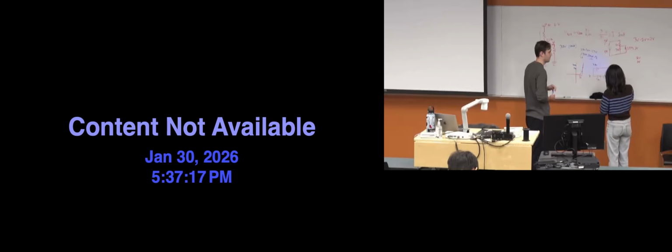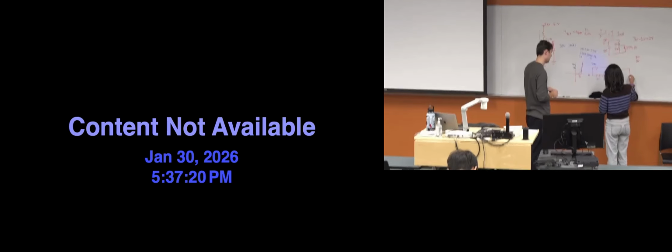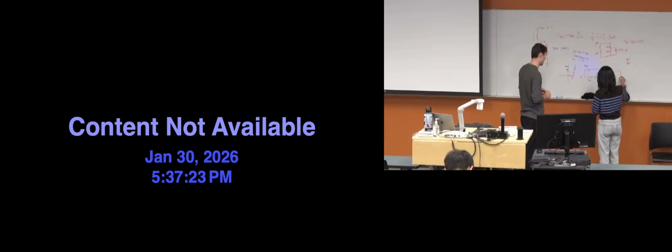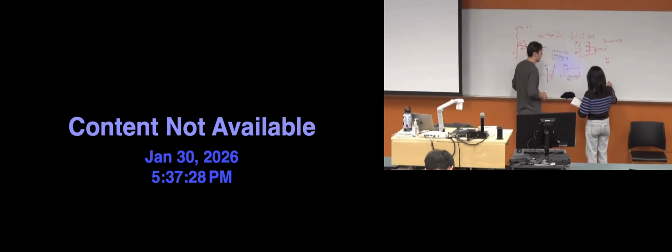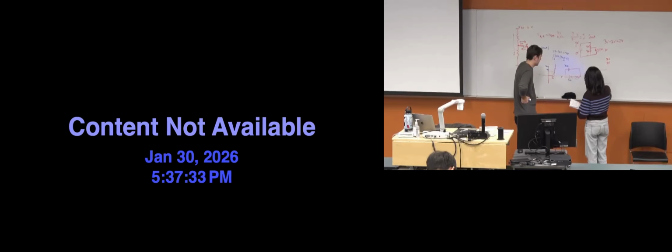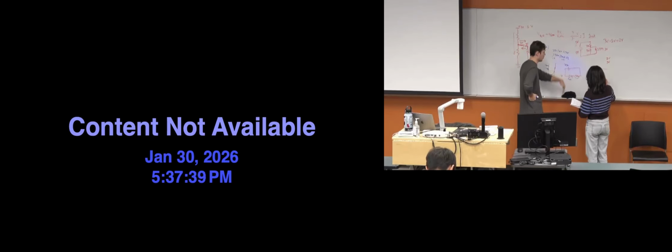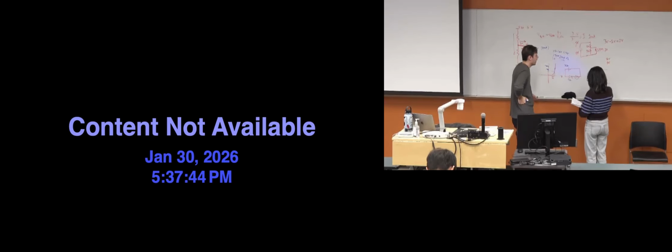You said that this was the Zener diode. It's just the diode, and it goes in the reverse direction, so it has a reverse bias. That's what we want, because that means current won't go through there under normal conditions. So it still has the same kind of curve. Under normal conditions there will be nothing going through this, and if the voltage goes higher than the breakdown, then current will go through.